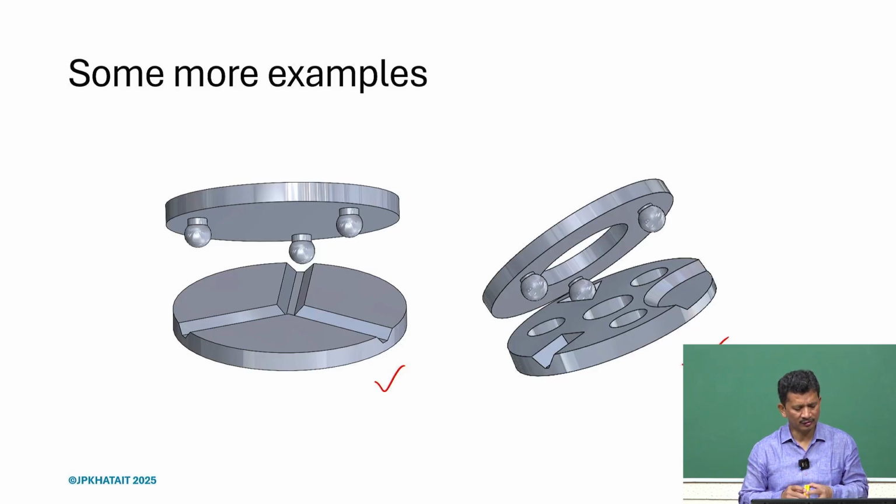What we see here is there are grooves. I have one here, and maybe we'll show it in detail in videos later. Here we have the grooves and a spherical ball joint, and they come in contact, and because of the design itself, the location is defined.